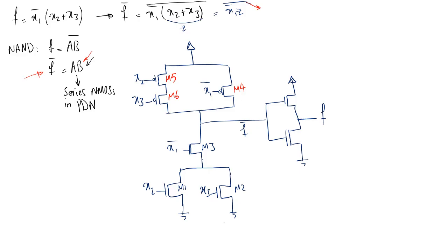But for this example that we're just solving right now, the F bar has a big bar on top of it that we have to address, right? So the first thing we did was build whatever is under the bar, and then we inverted the result. Okay, so now let's analyze this and compare it to what we had before. What we had before was 14 transistors and 4 layers. Here I have 1, 2, 3, 4, 5, 6 transistors plus 2 transistors. And then don't forget that x1 bar needs another 2 transistors, to create it from x1, right? So we're really talking about 10 transistors.